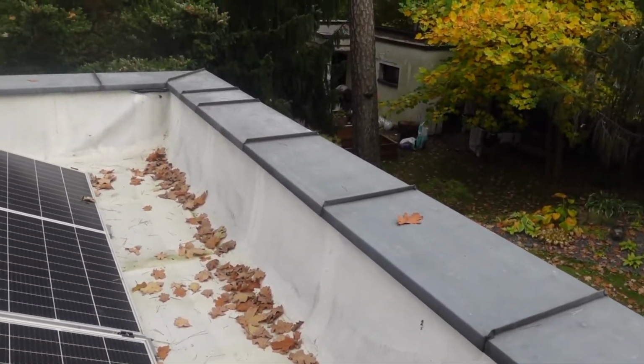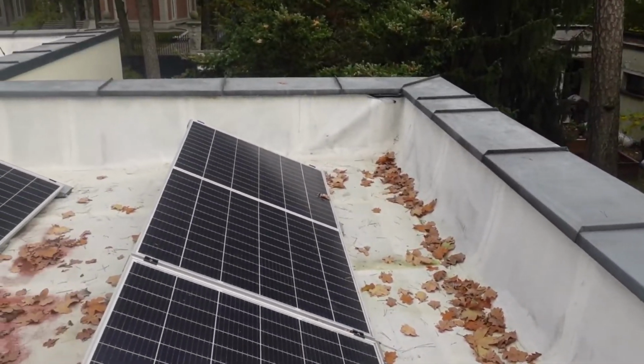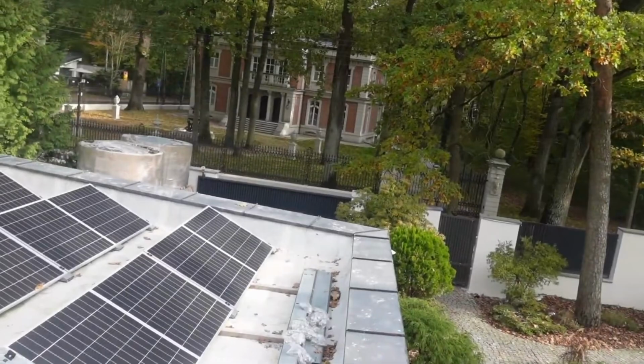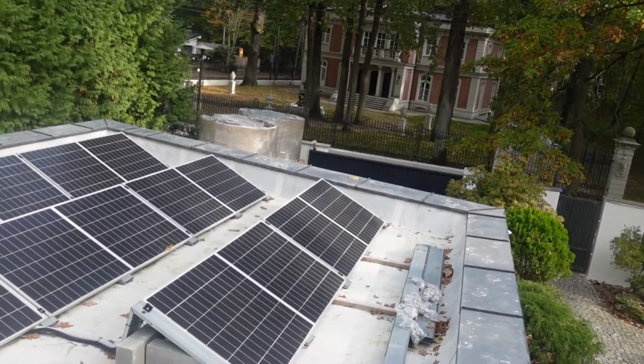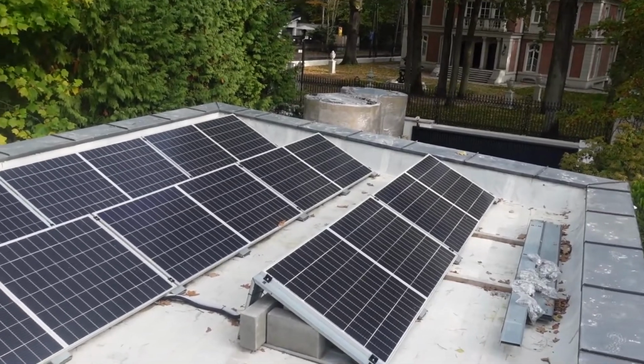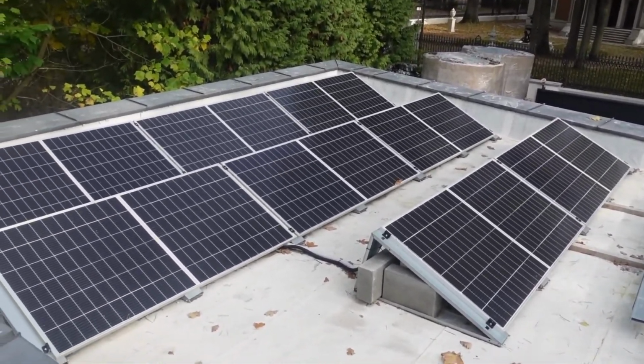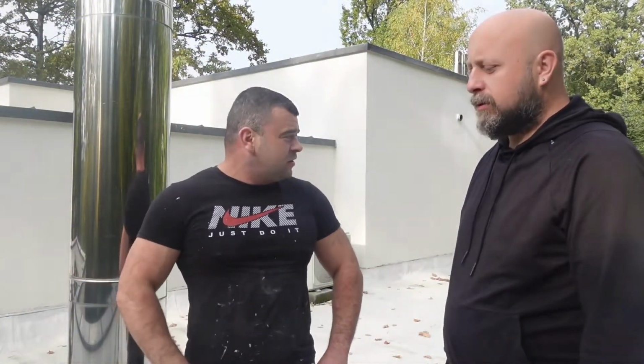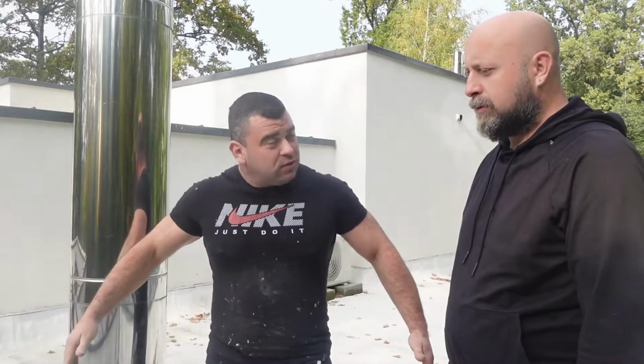This is really what distinguishes this roof, a special feature that will ensure the roof certainly lasts the next 25 years. Here we specifically added white pigment so that the light would simply be reflected, because there is a photovoltaic installation which works with double-sided panels, and we simply wanted to compensate for the loss of light due to the overgrown trees, which have a lot of leaves and it's much too dark. So that the sunlight is reflected off the roof, and the solar panels also receive sunlight from below.